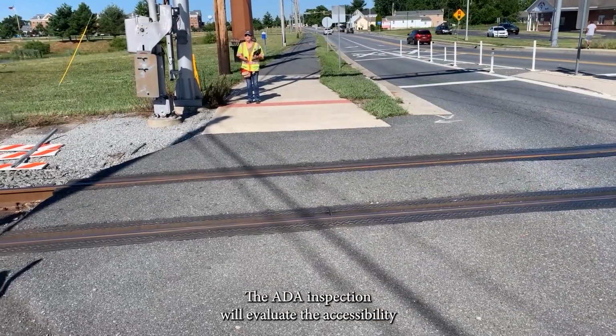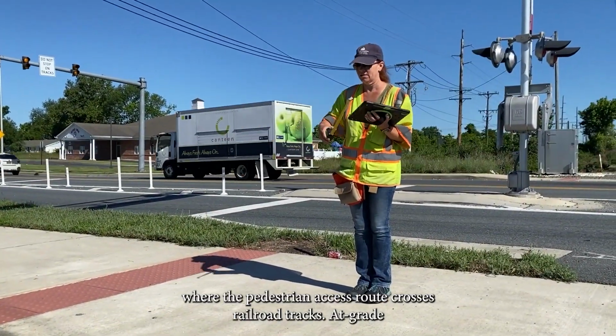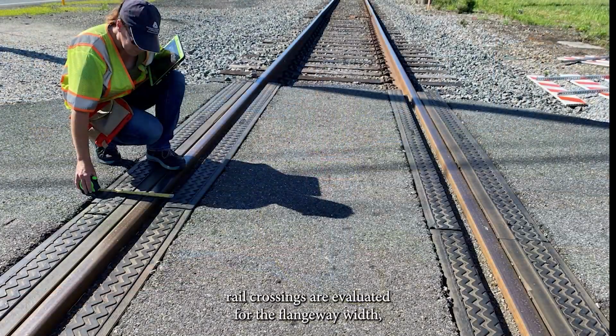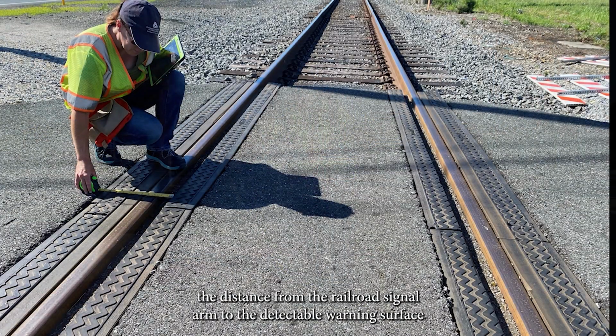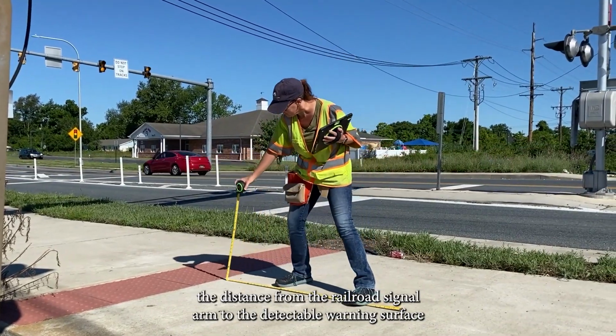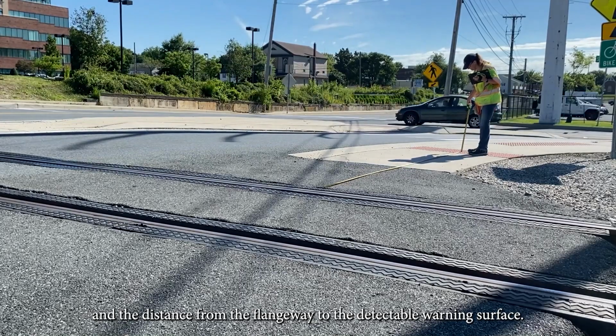The ADA inspection will evaluate the accessibility where the pedestrian access route crosses railroad tracks. At-grade rail crossings are evaluated for the flangeway width, the distance from the railroad signal arm to the detectable warning surface, and the distance from the flangeway to the detectable warning surface.